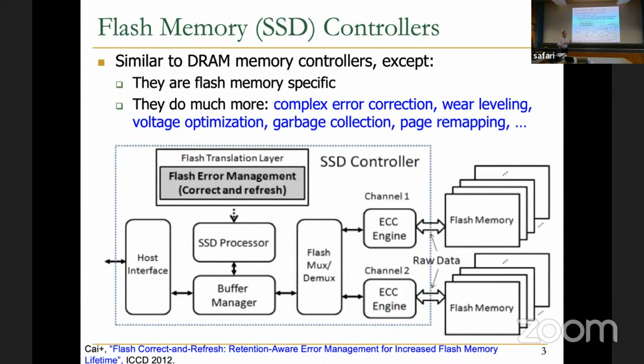There are multiple reasons why it stops working, but it stops working essentially. So it degrades over time as you keep writing to cells. So you need to manage that as well. So this doesn't exist in DRAM, at least as far as we are concerned so far. Maybe it exists at very long time scales. In that sense, no one takes that into account. But in flash memory, it exists in real time scales.